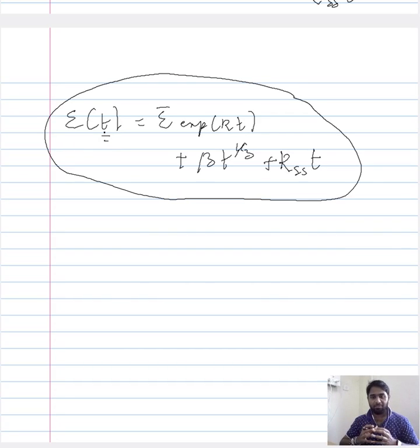Now, he was able to do this by sectioning the overall creep curve into two parts. The first part was a time independent one, and in this part there was an exponential increase in strain. So this is how we categorized the first part. Here the strain rate was constant. The small strain exhibited by the material was independent of time.